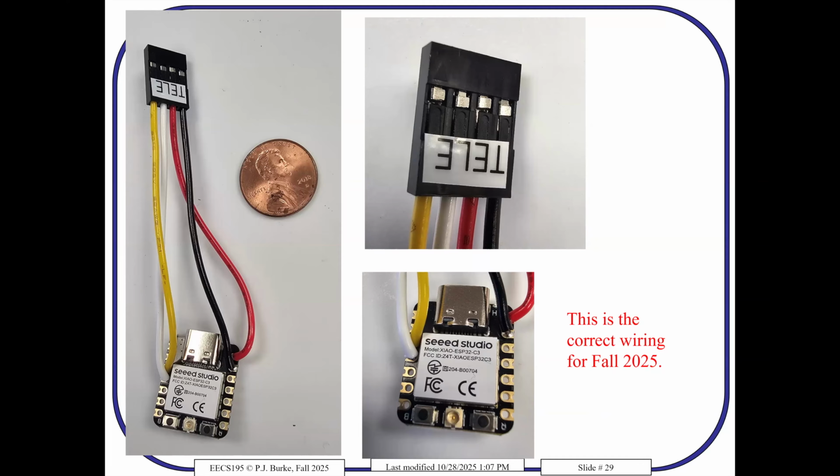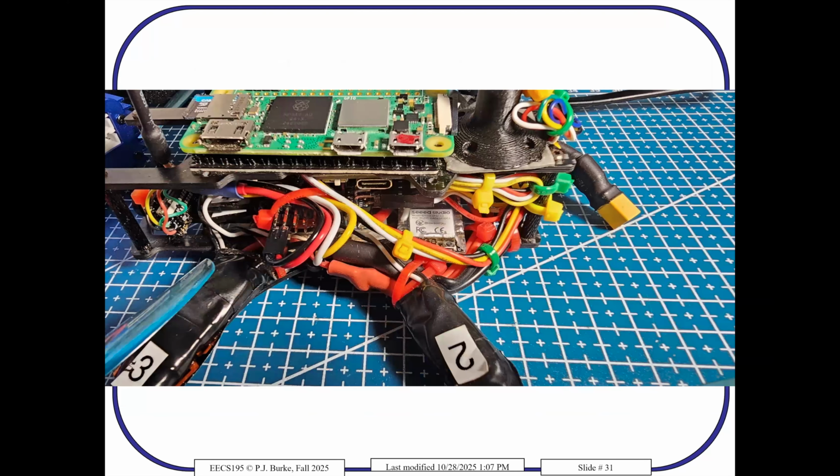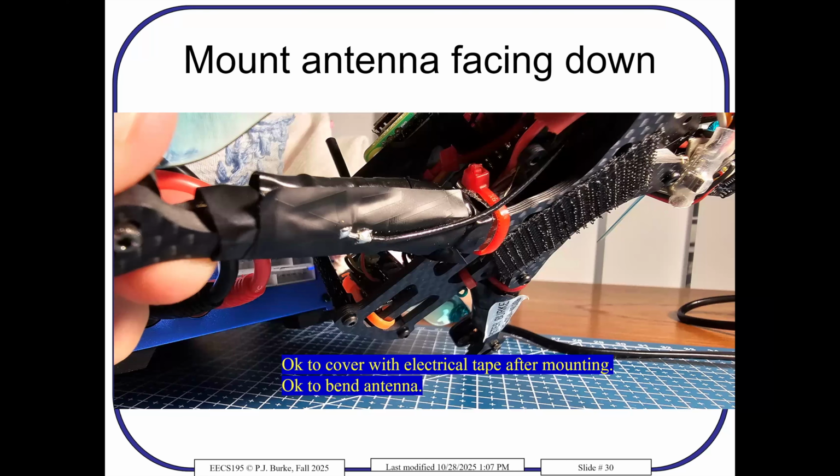So that's pretty easy. I put my antenna on the arm facing down so that the radiation pattern is down, because the drone's in the air. I don't want to send Wi-Fi up to outer space. I want to send Wi-Fi down to the ground. However, if you fly way out and land way out on the other side of the arc on the ground, you might lose connectivity because the antenna is facing the ground, and it's on the ground.